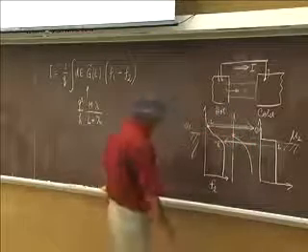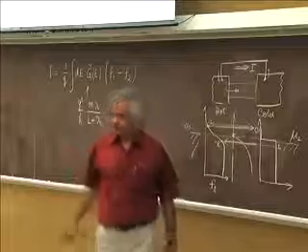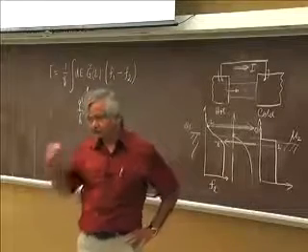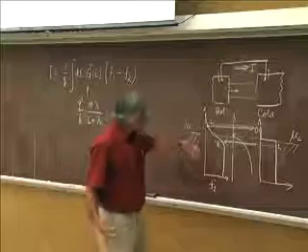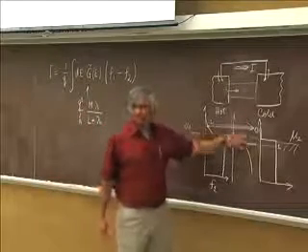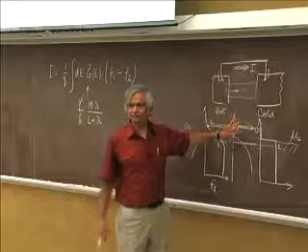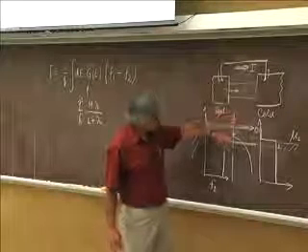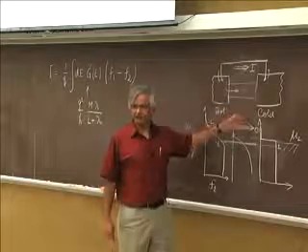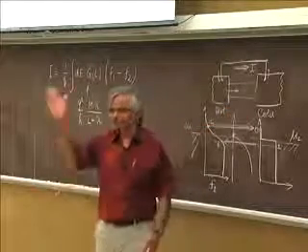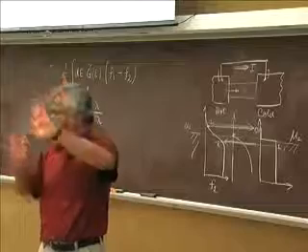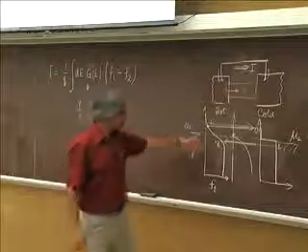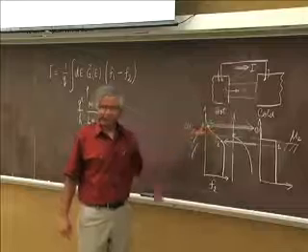But one point I should make is that if you looked at the Hall effect, because one of the things in this discussion I've tried to do is we have said that all that matters is really density of states. We don't have to distinguish between conduction band and valence band necessarily, right? Because usually people say, well, those are two very different things. You treat electrons separately, holes separately, right? But what I'm saying is not really. You can just treat the entire density of states altogether.